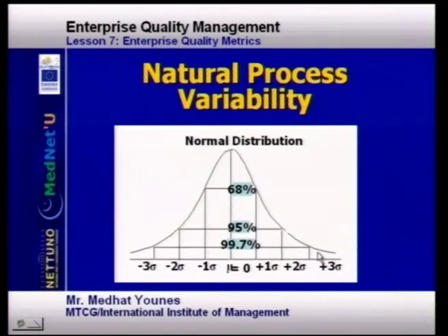You'll see in the natural process variability graph that the process variations can occur due to several causes like temperature variations, clearances, distortions, measurement errors, etc. When each cause is held to its practical minimum, the resultant process variability is called natural and follows a normal distribution as explained a few seconds ago.